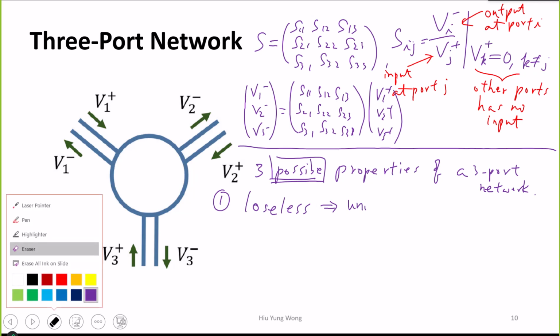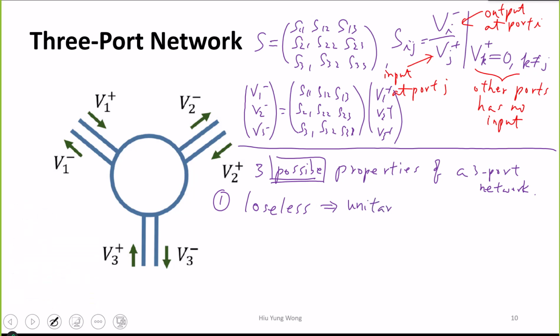So you see microwave is very similar, has a lot in common with the quantum computer. And indeed, I saw an article before where, when you introduced quantum computing to the microwave engineer, it just used the scattering matrix. And indeed, you can use any circuit, n-port circuit, to model a quantum gate. They will be exactly the same. However, the number of ports goes up with 2 to the power n. So if you want to model a 5 qubit gate, you need 32 ports, right? Because each port represents one of the components.